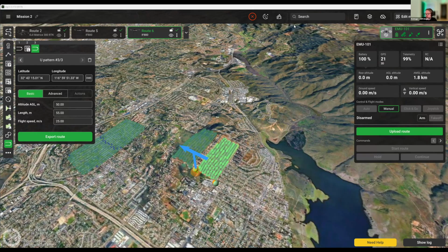But for some drones like the DJI Air series, one workaround, again, it's not really official, is that you can do the flight plan, and then since the remote controller, so the DJI Fly app, will save a KMZ file, then you can replace that KMZ file with a file from UGCS or some other planner. But again, it's a bit of an unofficial way and requires a bit of technical know-how on how to exactly replace the files.